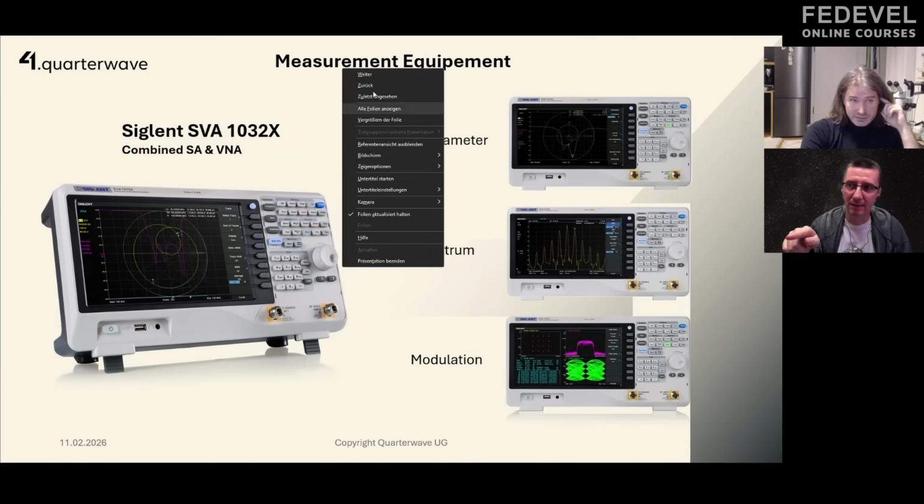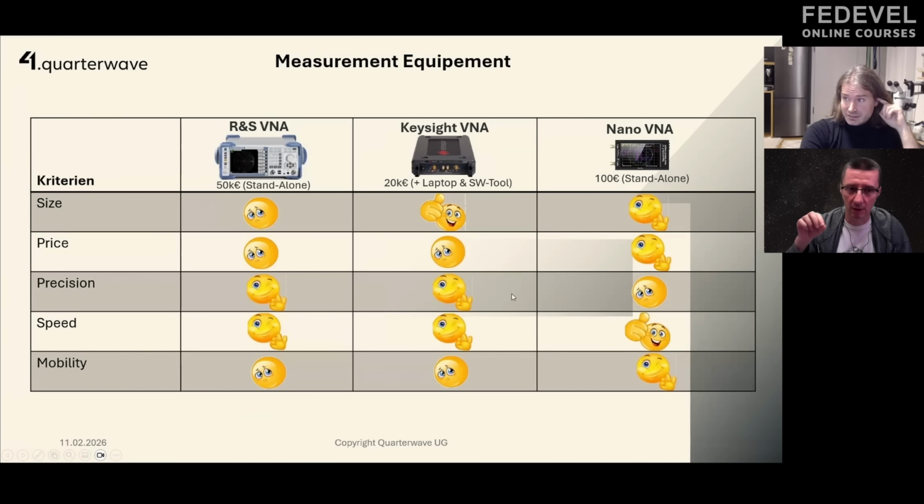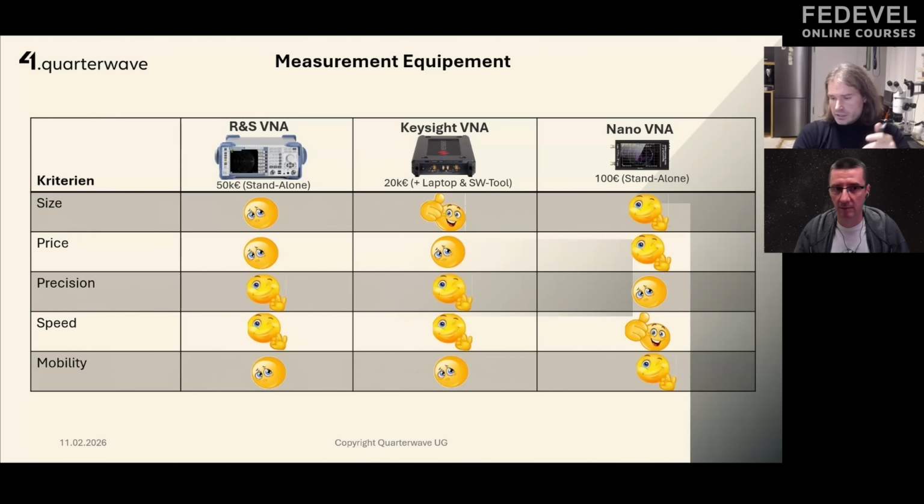So you need to connect this to the input of the antenna, correct? Yes, I need to put this on the antenna. You can see it here on the video. Here I have my network analyzer. What I need to do is put my antenna on that port and measure the reflection coefficient. But before I do this, I need to calibrate my network analyzer because I don't want to measure the cable. I want to measure only the antenna itself, and therefore I need to calibrate my network analyzer. And I can show you.